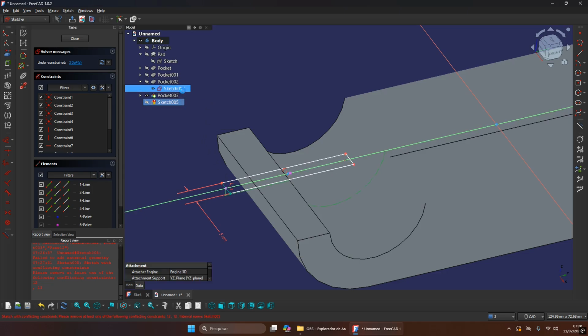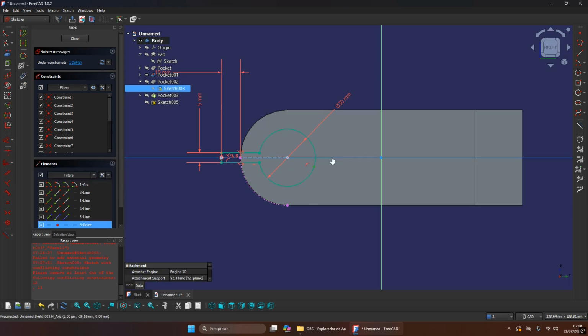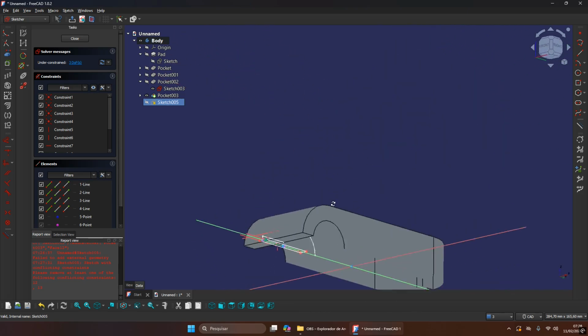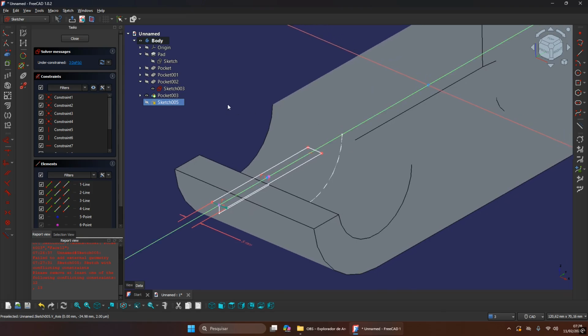You can go back on sketch tree and create a point here. You can go in the point command and create a point here. This point is not fixed yet. Let's create a coincidence between this point and the horizontal axis. Okay, now I can go back on sketch tree, and I'm already seeing that point. It's right here. Just use the projection command and try to select this point. You see? Now we can create some dimensions here.